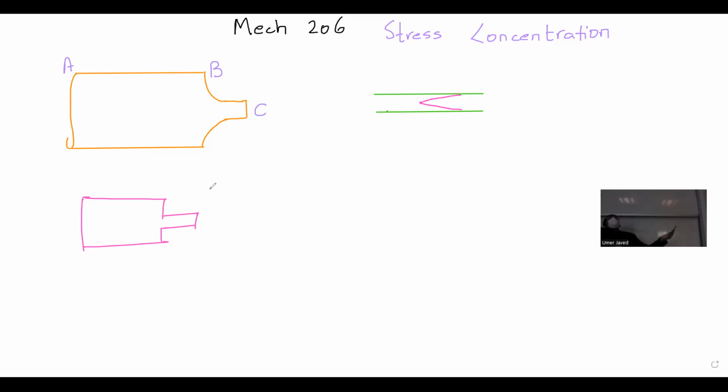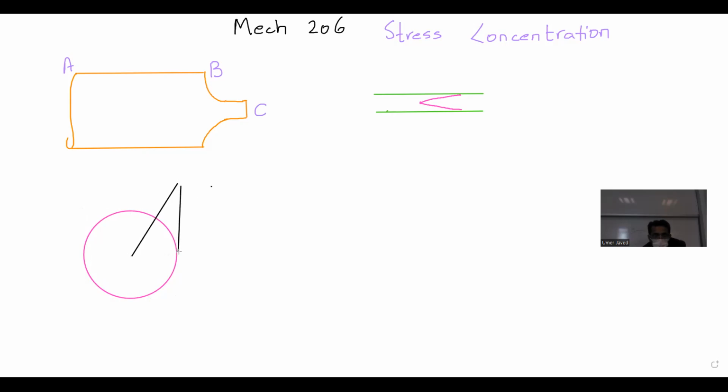So in this torsion topic, we will actually go for the same strategy. Now I have a shaft that is rotating, with a sudden change in the dia. And now again, I will talk about a stress concentration. Now for students who are like, come on, what does that even mean? Well, my point is that you have this nice and beautiful circular shaft. And if you remember, for torsion, the shear stress is equal to TR over IP, behaving somewhat like this. I will give my best shot in this drawing. I used to tell you, nice and beautiful, boom, right?